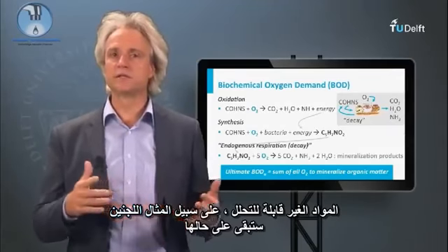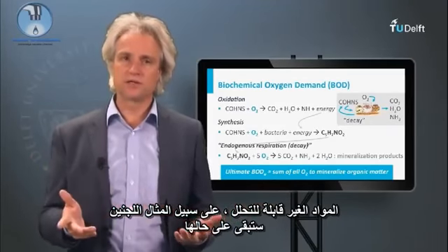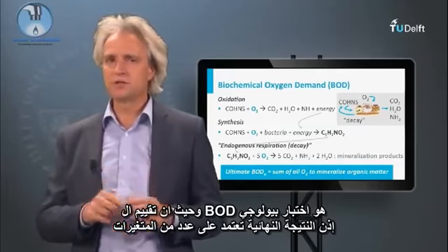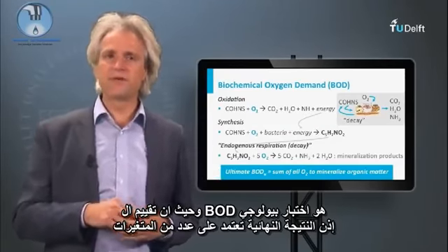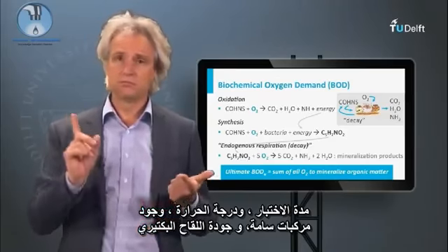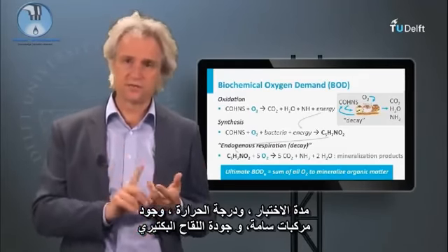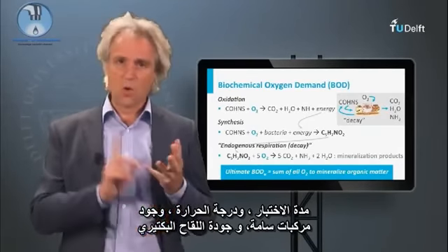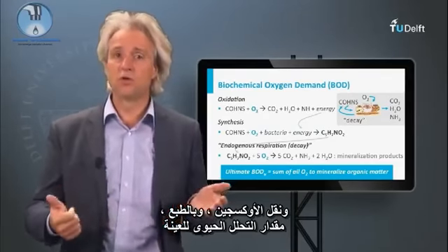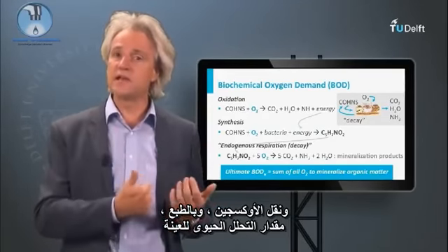Non-biodegradable matter, for instance lignin, will remain untouched. Since the BOD assessment is a biological test, the final result depends on a number of parameters: test duration, temperature, the presence of toxic compounds, the quality of the bacterial inoculum, the oxygen transfer, and of course the biodegradability of the sample.